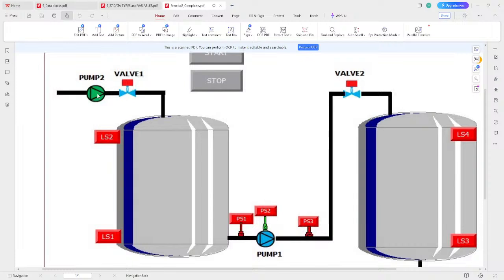Manual mode for the pump, everywhere will be green, here will be green, and here will be black. And when it's stop on manual mode, here will be black, here will be blue. That is for manual mode. If it's on blue, you know you're on manual mode. If you're on auto mode, everything will be green. Both this is green, the box inside is green, and if it's on stop, everything is blue.